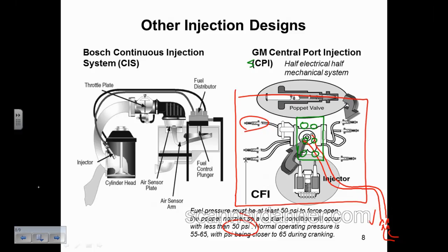So now instead of having them all fire at once, and a lot of people say if you fire them all at once, that's a waste of gas, right? No, we time the injector spray. It fires 1 time per crank rotation, so it actually fires twice before the intake valve opens, and we time that spray to be the right amount. It just sits there for a period of time before the intake valve opens. How long is that period of time? It's only a few milliseconds at idle speed between intake valve openings. So it's really not that long. And they were very efficient.